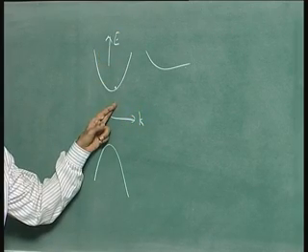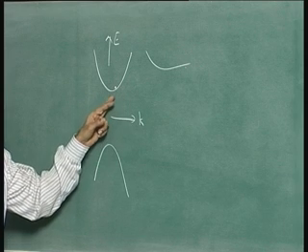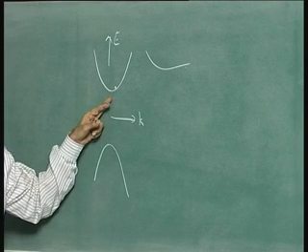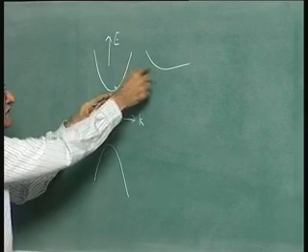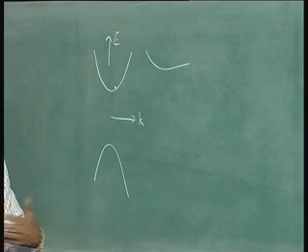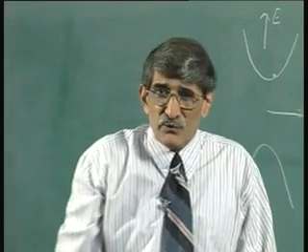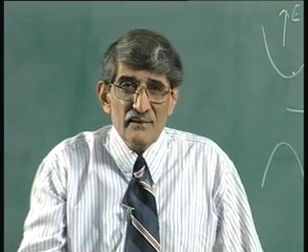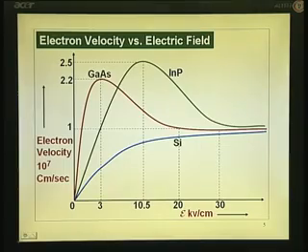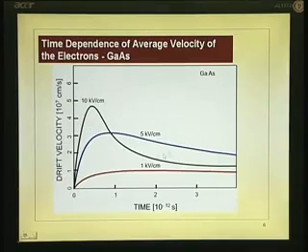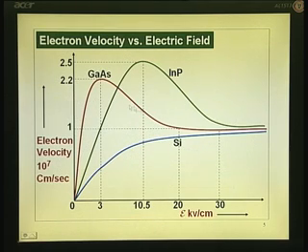All the time here during the transient time, and if you subject them to a high electric field, they accelerate much faster. So, they even cross this energy, and during the transient, just as in networks when you subject them to a sudden pulse, there will be overshoot effects. Similarly, you get the overshoot effect because of that. So, if you subject it to 5 kV, it goes up, then ultimately if you wait long enough, it will saturate onto the steady state velocity governed by the 5 kV.